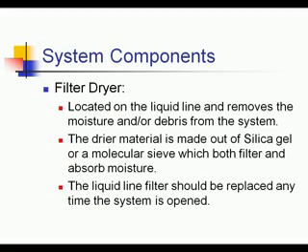So the entire cycle here, we start at our compressor, we move through our discharge line into our condenser, out of our condenser through our liquid line to the metering device, out of the metering device to the evaporator, and out of the evaporator through the suction line back to the compressor.